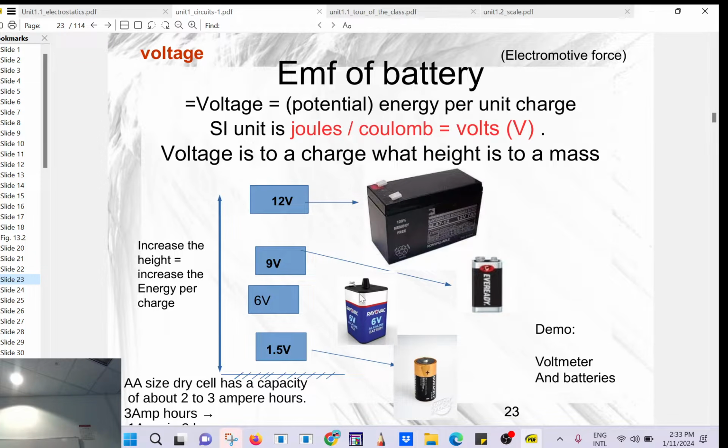And here I have what you expect. I have 1.5. I have cheap dollar store batteries. So 1.5, 1.5, 1.5, 1.5. About 6, right? So let's see. They are in series. So let's see if it works. 5.7 volts, right? Are you with me? So that will be a voltage drop.